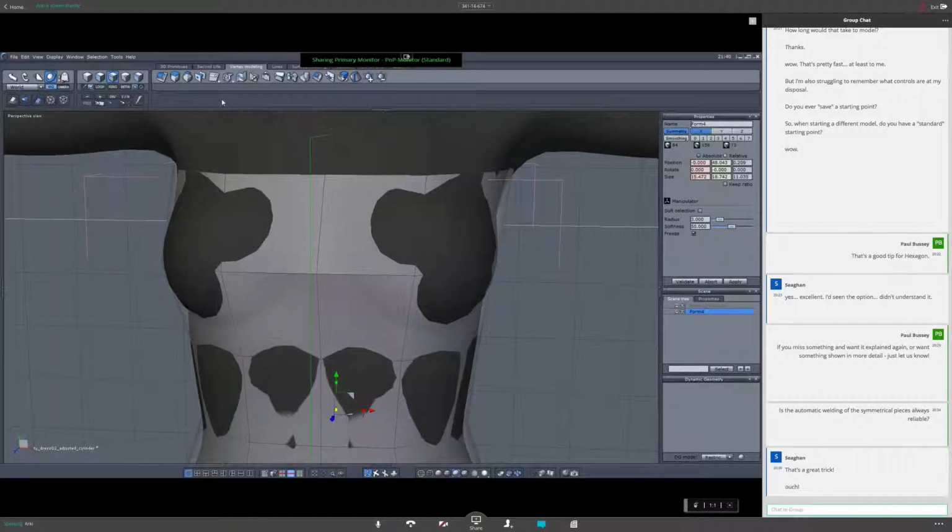So when I want to do this, I have to use one of these tessellate tools up here. There are several ways to do this. We have free tessellate. You can point and click almost everywhere on a polygon, and in theory, Hexagon should add a new point and a new edge right there, but in practice it crashes. I use this one. This orients itself by existing edges.